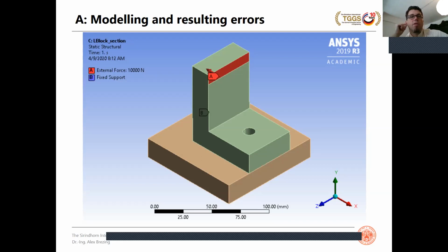And that's it. Now the resulting error, of course, will be that there will be no internal stresses resulting from the bolted connection here. What is most important here is that these two parts are really united, and we can expect they're trying to bend. Now you can even calculate that these two united parts will have a much higher stiffness against bending in this horizontal plane. If you would calculate that, the moment of inertia would not be only the sum of the two bending moments of inertia, but we even have a term, and that is really big according to the parallel axis theorem. Basically, this is a sandwich, right? And we know in real life that's not correct.